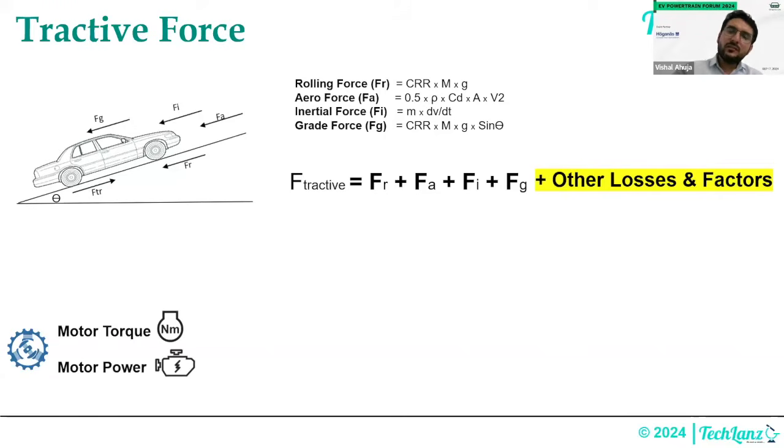Then based on meeting your max power condition, like the max speed condition, when you're trying to drive a vehicle, you understand, okay, what's my max power requirement? It can come from max torque and base speed also, but typically comes from the max speed condition. What's the max speed of the vehicle you want to drive and what acceleration level you want to give at that condition, right? Then you get these kinds of things.